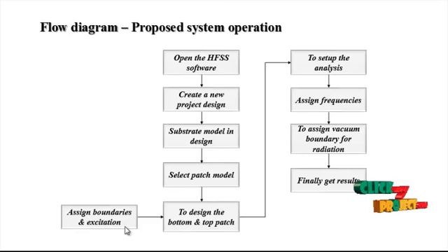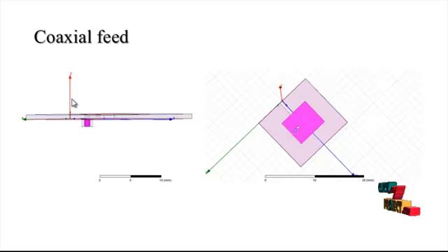So the figure is shown. Yeah, this is one type of coaxial feeding, at the bottom of the process. The inner part is a coaxial probe, the coax pin, and the outer coax. So this is called a coaxial feed using the excitation of the wave port.